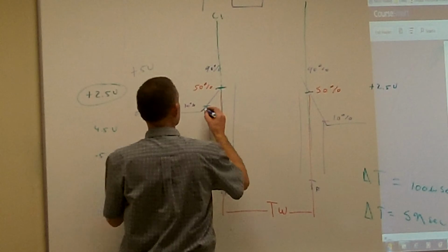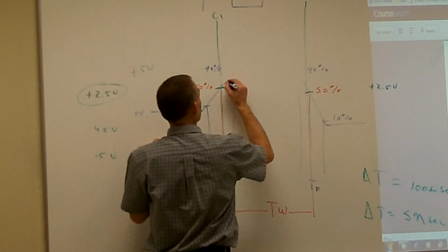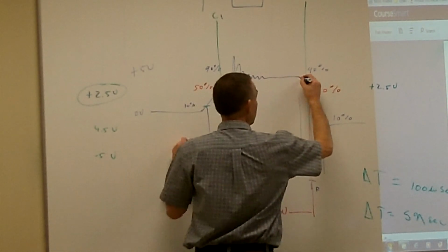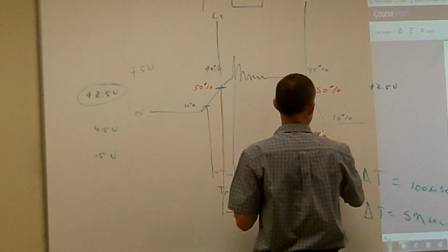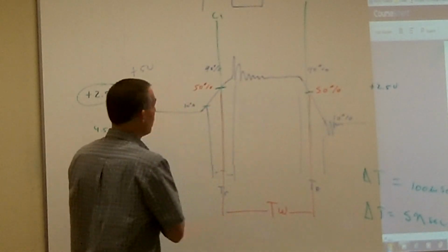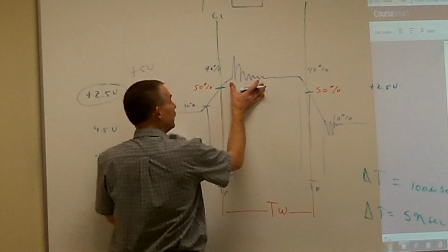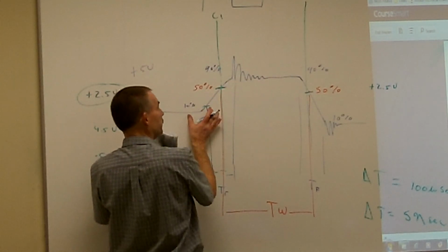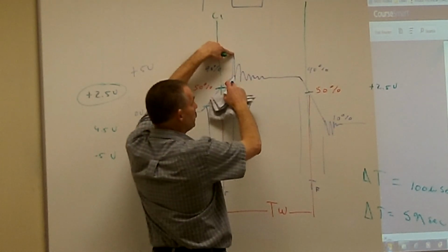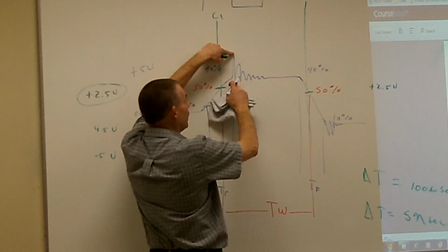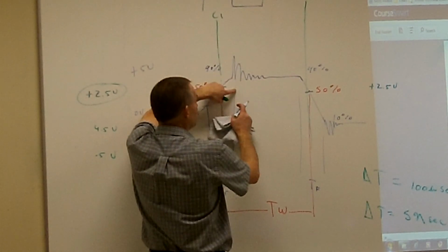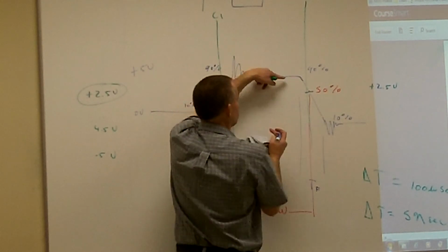That square wave, when I get zoomed in on it especially, is going to look something like this. It's going to go up, and then when it goes down, it's going to do the same thing. And so you're going to get what we call ringing. The transition between this thing going from 0 to 5, it's going to overshoot it. Then it's going to try compensating for it inside the circuitry, inside the oscillator and the function generator. Then it's going to undershoot it, overshoot it, undershoot it, and then finally it stabilizes out.